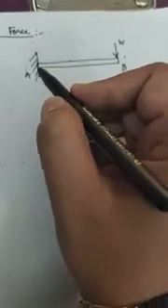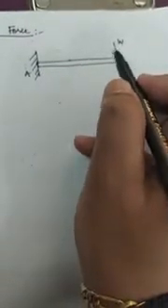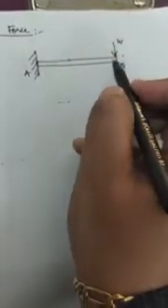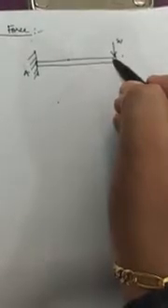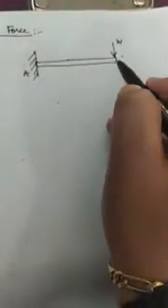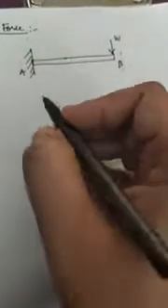So whenever a beam is being loaded, internal stresses will develop in the beam. Stress is force per unit area. And the vertical load acting on a beam will produce two effects. Either the beam will fail due to shear, or it may bend.